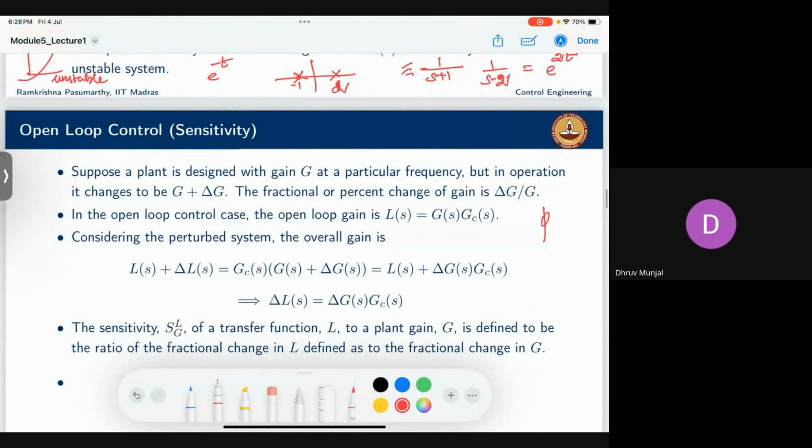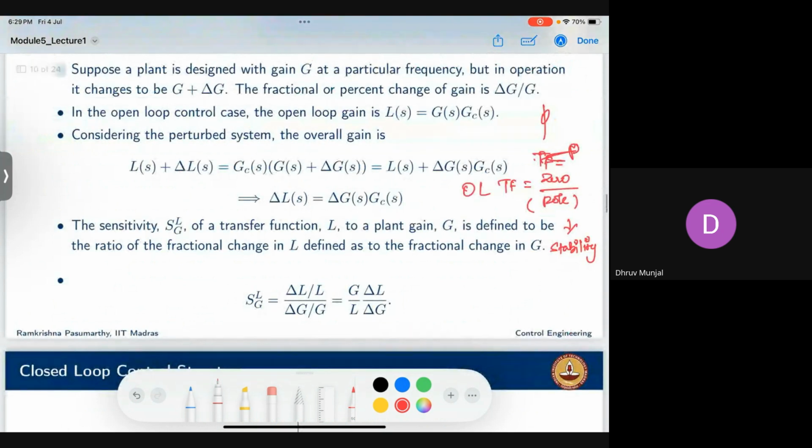See, usually if I write a transfer function, this will be the zero, this will be the pole, right? All these poles, we consider for stability. This I'm writing is for the open loop transfer function. So when I write a closed loop transfer function, where this is your G, your G will come as G over 1 plus GH. So automatically the G that has zero and pole, this zero will come here, and finally this would become a pole for a closed loop system, right?